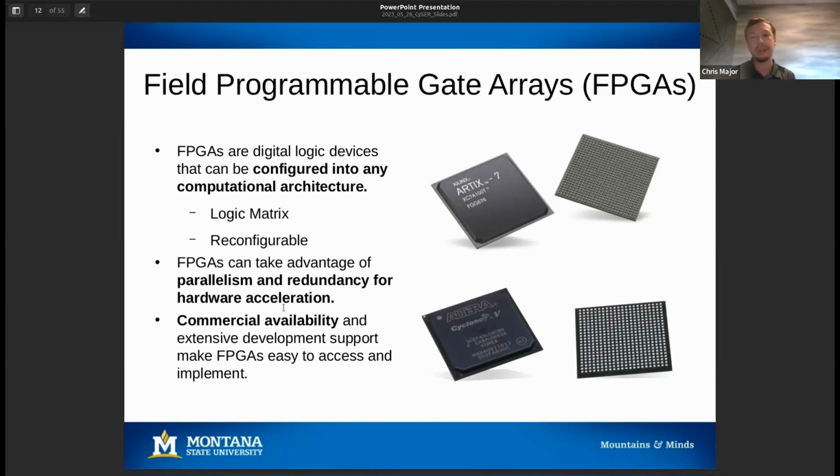And depending on how you reconfigure those blocks, you can create any sort of logic circuit possible. You could create a processor, you could create a digital audio converter, you could create a small network cluster of processors. But the point being that an FPGA in the developer's hands is reconfigurable. So custom hardware can be built and executed on this device to solve a problem.